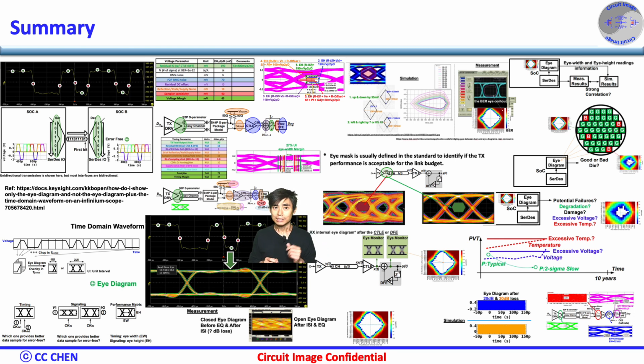To make sure the ecosystem works well, most specifications also define the TX output eye mask strictly. Besides the external eye diagram, recent high-speed SerDes has the internal eye scan or eye monitor after the CTLE or DFE for both design and silicon validations. In addition, the added internal eye monitor not only improves the yield during the production or ATE test, but also enhances the reliability in their lifetime.